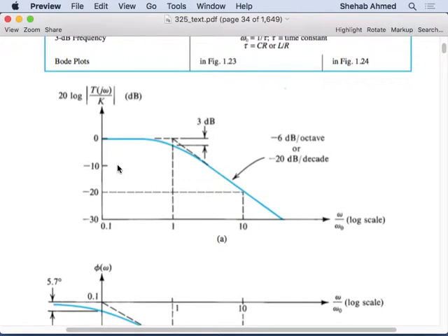In some cases, it wouldn't fit the format? No, with a single time constant, it will always fit, either this low pass filter format or the high pass filter format. And we can tell if it's a low pass or a high pass by the capacitor position. Yes, you should be able to do that. So that's something we should know.